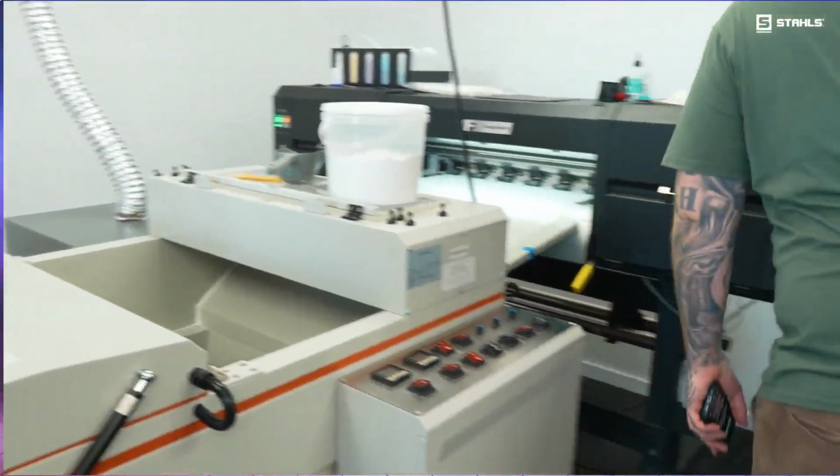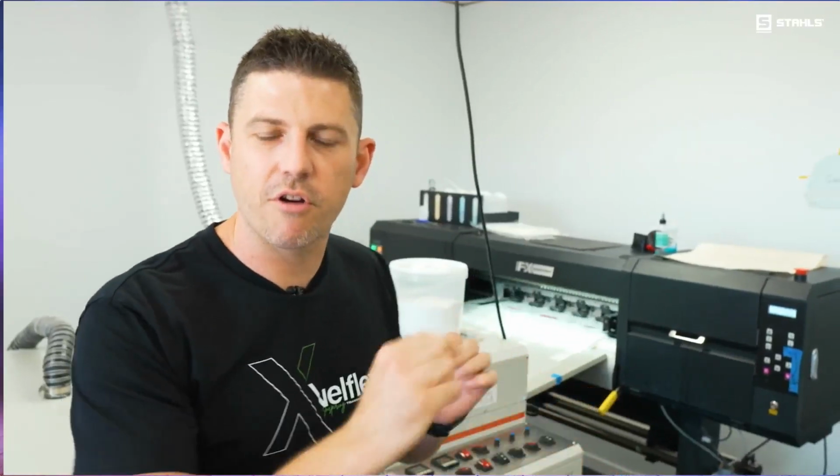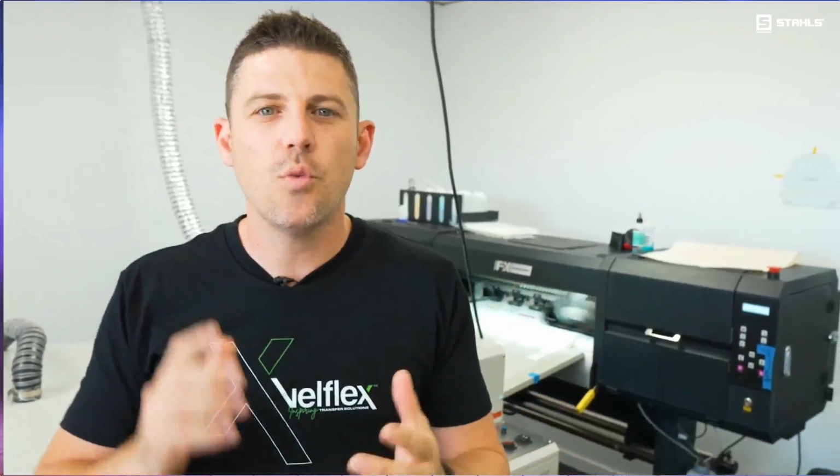All right guys, so here we are now, we're in the DTF room. DTF stands for direct to film, okay? It's an iteration of direct to garment where obviously they're printing directly onto the t-shirt, directly onto the fabric. Whereas direct to film has a second stage, and instead of printing directly onto the product, they're printing onto the film, onto a plastic liner, okay, which is creating a transfer, which is then heat applied onto a garment later.